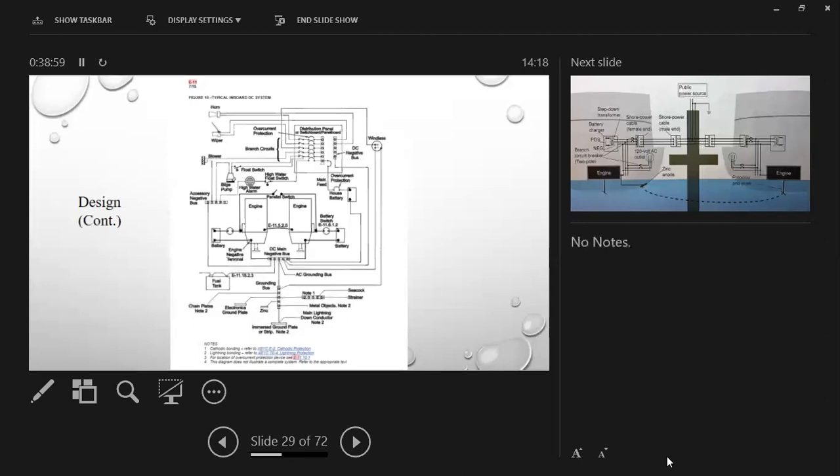For protection against electrocution or shocking, right? If there's any fault, ground fault, any place on this boat, since everything is tied together, that ground fault is going to go to your shore power system. It's going to go to your ground, okay? And not shock somebody on the boat. The fault is taken right off the boat through your AC grounding system, okay?